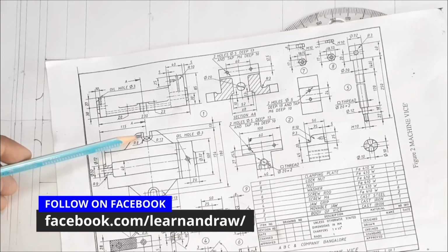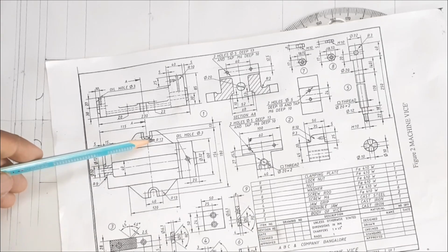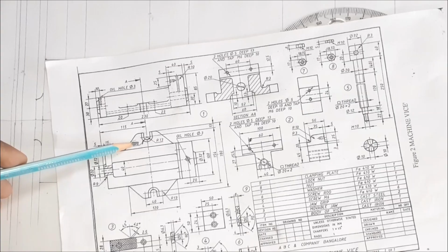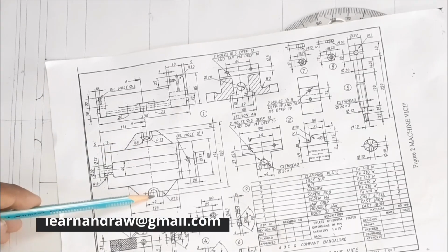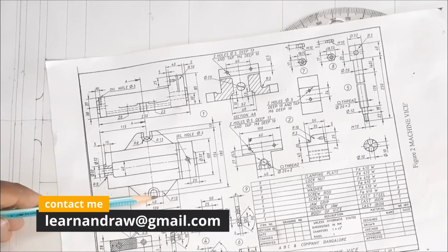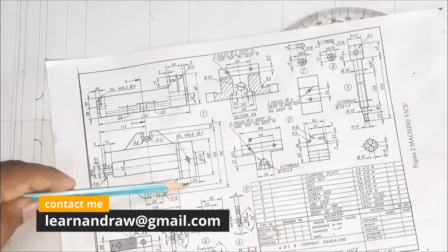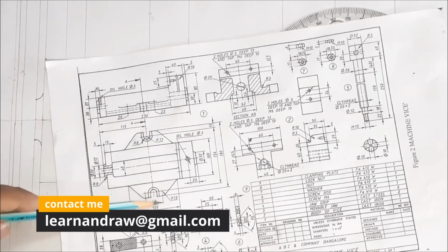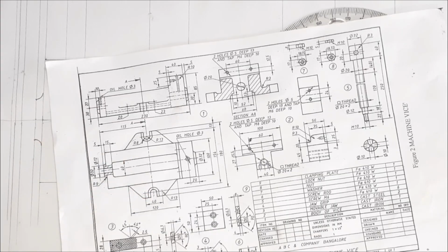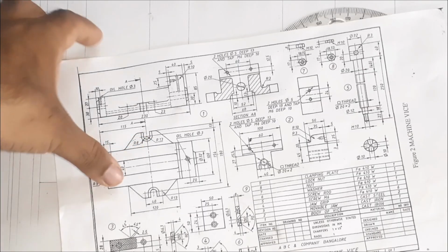Next step, there are 2 arcs, radius 13 and radius 8. So from this point we have to mark 8 mm, 13 mm, and similarly on the left side 8 mm, 13 mm. Then we have to draw this line up to 13 mm, so from here to here a distance of 13 mm. Next we have to draw 2 arcs of radius 8 and radius 13. First let us draw this one.